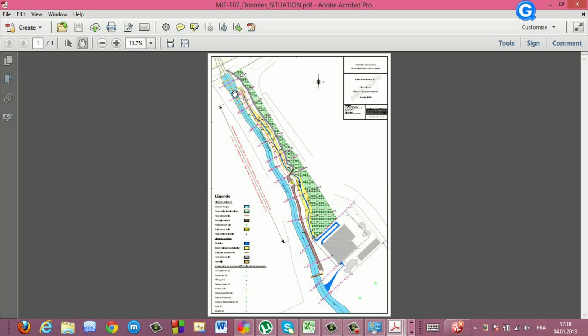It is going to be built here, but I think it's just simply a plan. It doesn't exist at the moment. And this one is the river. The cross sections are here from 1 up to 14. Because HEC-RAS starts the calculation from the downstream side to the upstream side, we have to put the first cross section here, not this one.